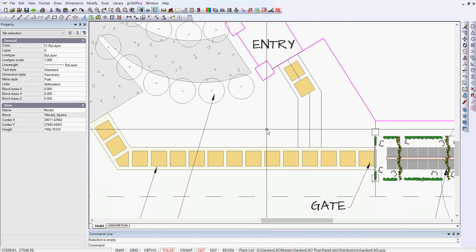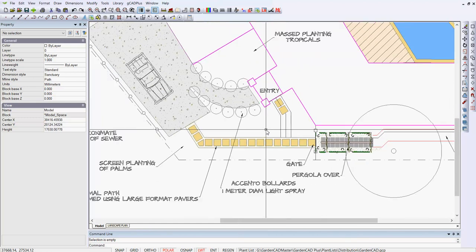So I hope you can see that using drafting settings, picking up the polar opportunity, setting step size and adding additional angles means that you can deal with designs where everything is a rather unusual angle. The sort of angles that architects just love on a site such as this, where you're trying to fit a lot of information onto a relatively small site.